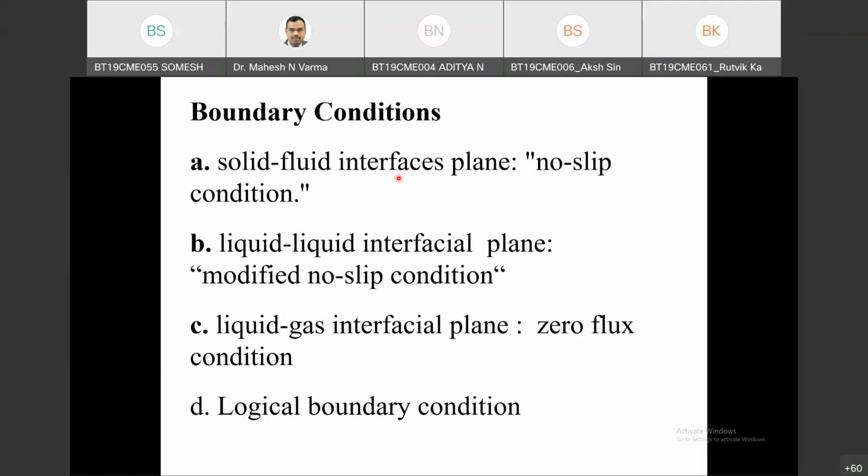But what intent do you want to get out of that? Assuming different radii, sir, the bigger radius will have bigger area, restricting more motion of the liquid, and the smaller cylinder having smaller area, restricting less. No, no, that cannot be considered actually. That is a wrong assumption. We are assuming the first layer of the fluid in touch with the solid will have the velocity of the solid because this is at the interface.